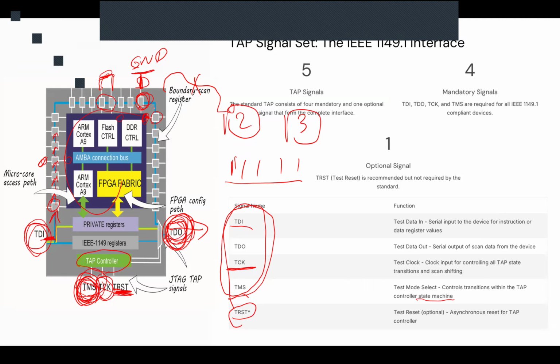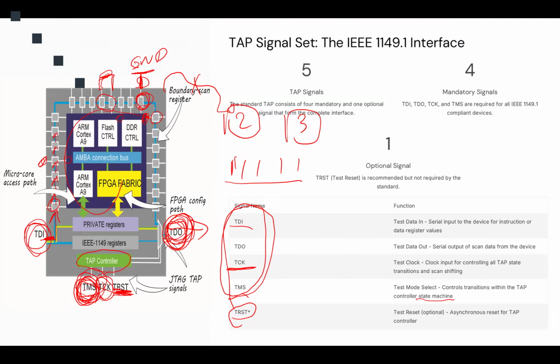If these two are mismatched, or not aligned with each other, then you read the wrong data at the time. So this is why the timing constraint is important, and clock crossing is an important consideration in JTAG testing. Now, this is the discussion that we had for today.